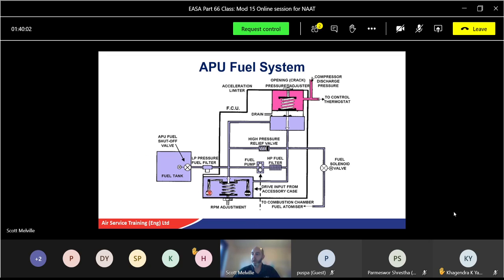Okay, again, that'll sense that there as well. The electronic speed switch assembly receives speed signals from the APU mounted tachogenerator, your speed sensor. As the APU passes through each control, we're going to look at speeds of 35%, 95%, and 110% relay switch. We'll just look at that shortly, and they'll do different parts.